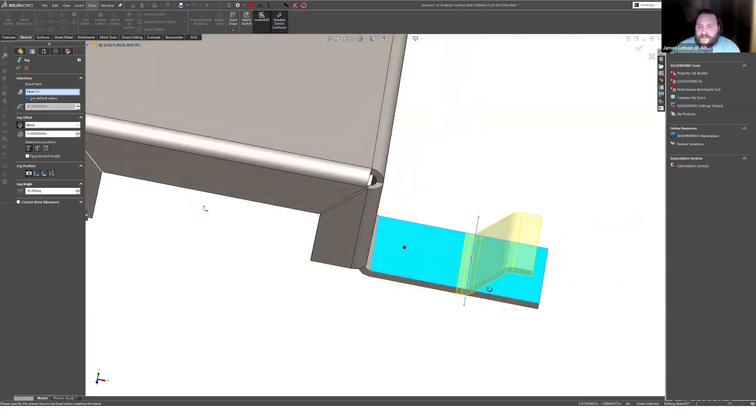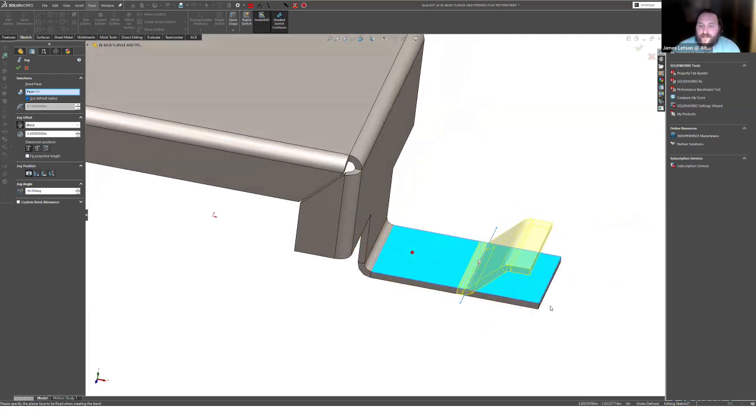If you designed this knowing what you needed your flat length to be, you would uncheck that because you knew, okay, I wanted it to be 6 inches flat and then apply the jog. And I can check it back and you can see it's just adding material here. It's just a cool feature that I feel like gets overlooked.